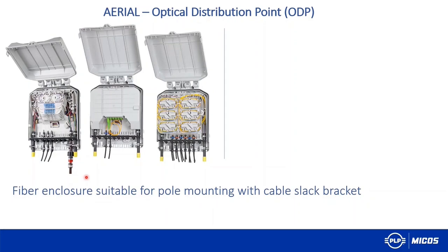It means from the pole directly to the facade of the house, somewhere 3 meters high. Connect the cable, drill the hole, and go inside the building, or end it in an FTP in a small outdoor box.